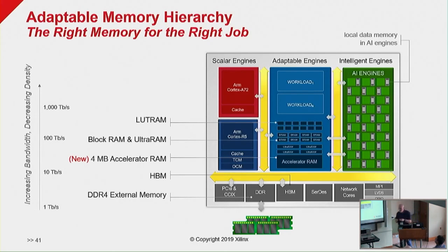Now, one of the key things about this 7-nanometer game, if you will, is that the transistors scale, but the wires don't scale. So that's one of your problems. The second problem is the biggest problem in compute today is not so much compute as getting the data to and from the compute. So all these level 2, level 3 caches and all these flushes and misses, they just really hurt you.